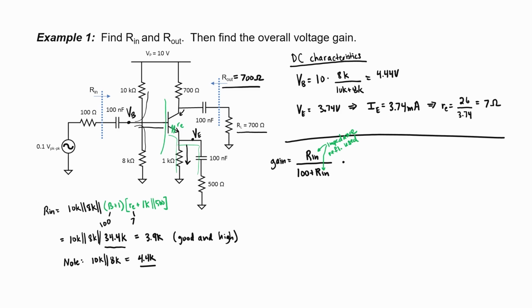We now have our gain section, and the gain of a common emitter amplifier is just the collector resistance divided by the emitter resistance. When I find the emitter resistance here, I'm not going to use impedance reflection because I already used it on the input section. Therefore, we have the resistance at the collector, and then for the emitter, we're going to stop at RE. We now have a voltage divider at the output side set up by our load resistance and R sub C.